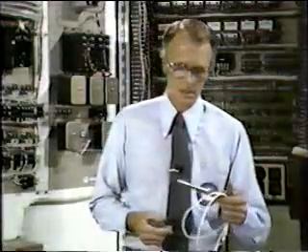Now, another component in the DC control system is the transducer. A transducer converts one form of energy into another. For example, the magnetic pickup, as seen here, converts rotational motion into electrical energy by electromagnetic induction. Two other types of transducers are used to sense heat in the turbine and generator. As an example, the thermocouple seen here is used to measure engine temperature. Resistance temperature detectors, otherwise known as RTDs, are used to sense heat buildup in the generator.